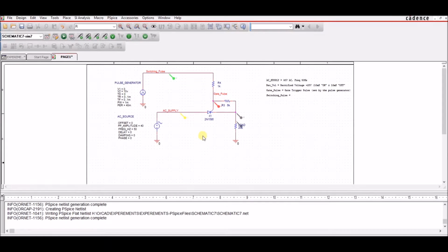So what we could conclude from this learning process is that it's a rectifier, but it triggers only on the gate pulse, and if you're giving a sine wave at the input, every time the sine wave goes to the 0 point, this resets, and you could control the power to the load with the help of the timing pulse that you generate on its gate.